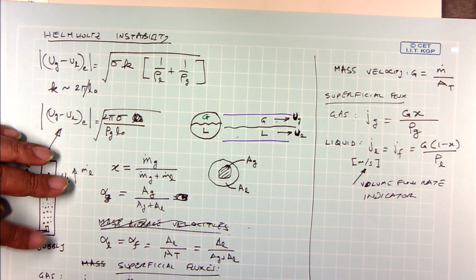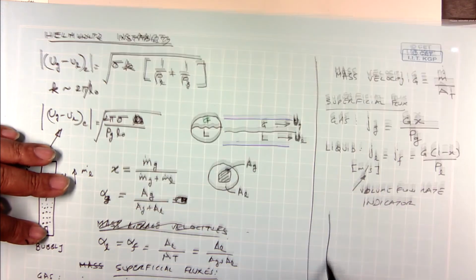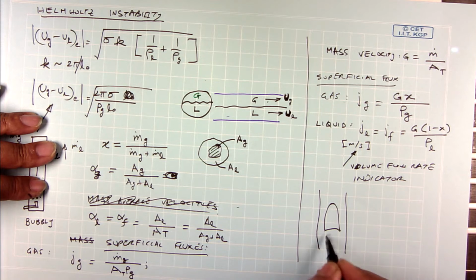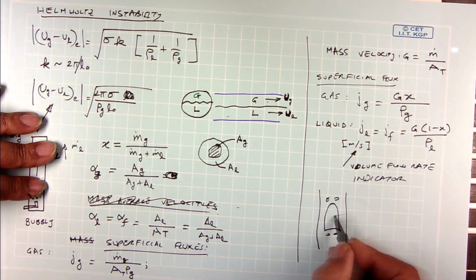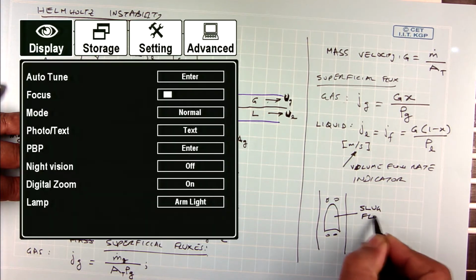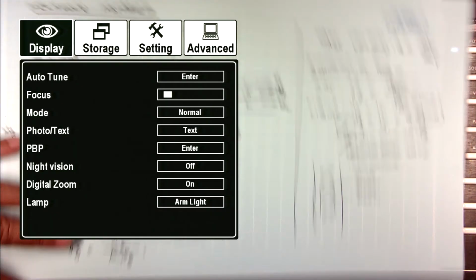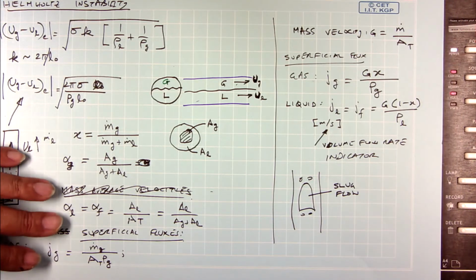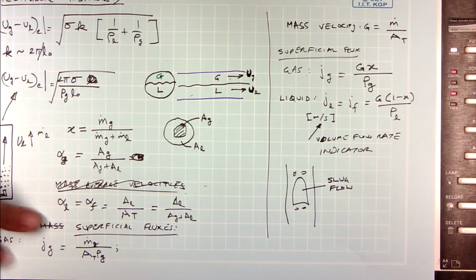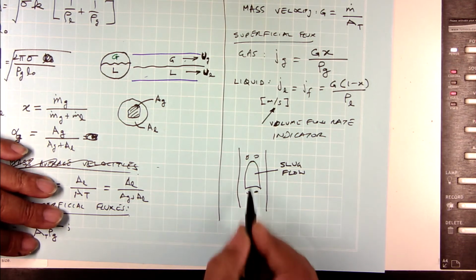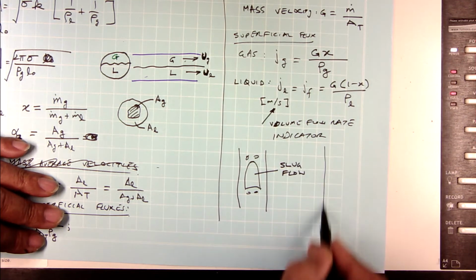When the bubbles are the same size as your pipe dimension, I end up with slug flow, where the size of these gas bubbles is of the same order of magnitude as the diameter of the pipe. And eventually these slugs start joining up and forming longer columns.